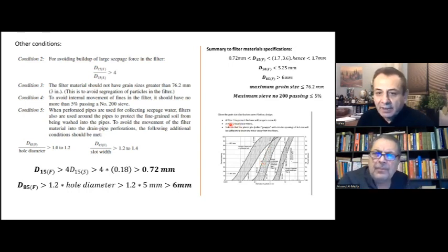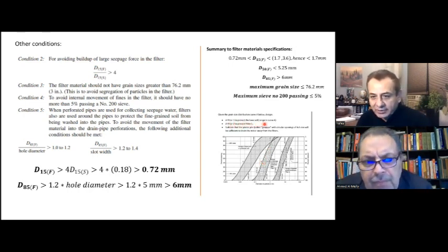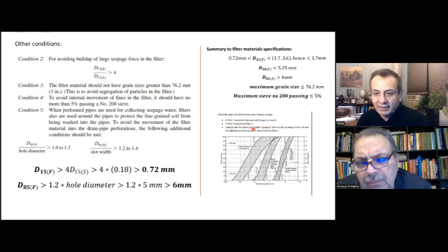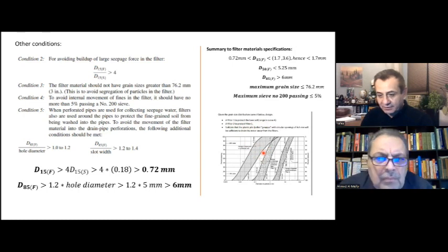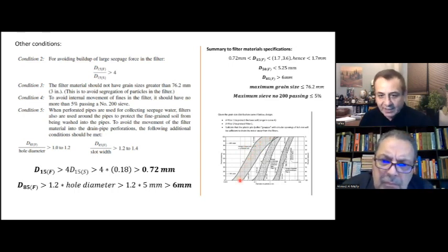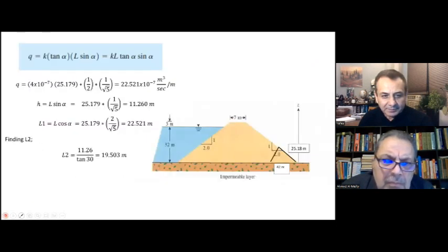Okay, so a filter 1 to protect the base soil in range curve A, a filter 2 to protect filter 1. So this figure is when we have more than one filter, like a successive filter. So I'm sorry, it's not related. It's just showing that we can develop an envelope for checking those values. But those are the most important values that we should check, D50, D85. Let me get back to a clearer one.